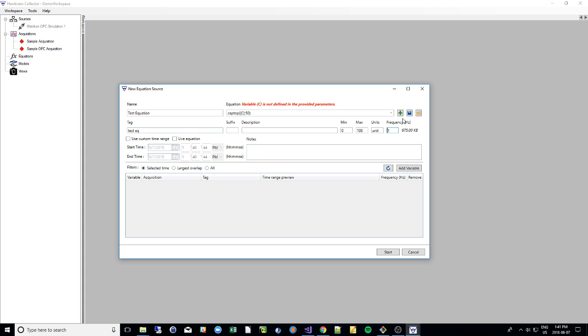So while you can sample at a frequency higher than your source ax, it's not recommended if you're using more advanced functions, because you're essentially pulling the same value several times, and if you're trying to do an integration or a differentiation, this may not work.